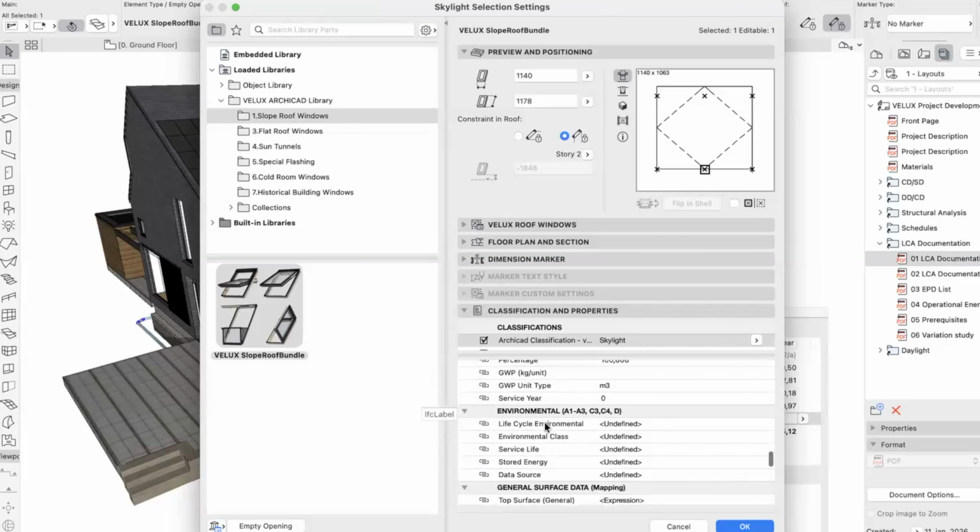But since this has to be documented for the municipality, for them to give us a use permit, I'll just want to show that part of the Danish template is these documentation layouts. And I can just zoom in a little bit. So here I have the whole calculation, 5.12. Then I have my area calculation for the areas of the building. I have the LCA per window and also for the VELUX skylights. And then I have for my doors here.